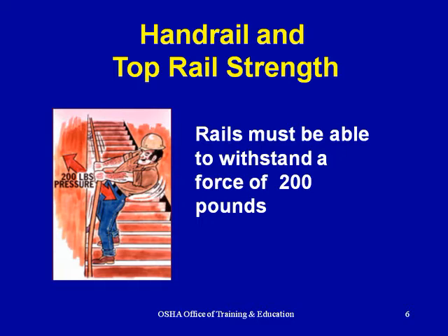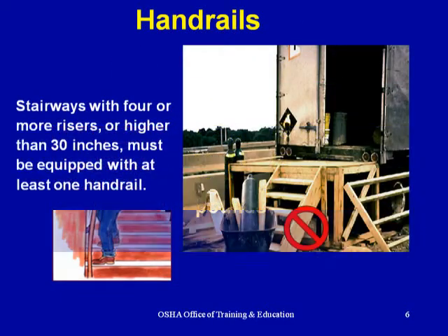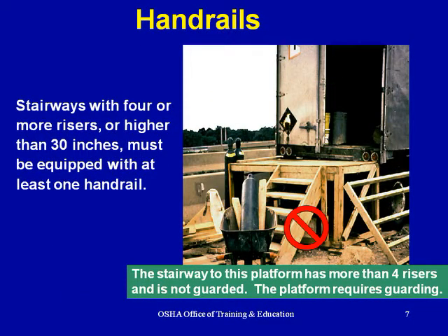Handrails. Stairways with 4 or more risers or higher than 30 inches must be equipped with at least one handrail. The stairway for this platform has more than 4 risers and is not guarded. The platform requires guarding.